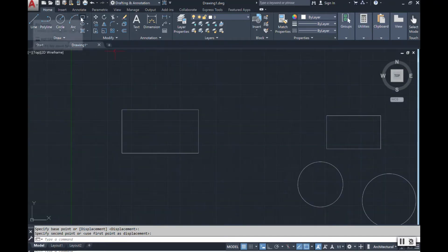Remember, when you pull in a rectangle, you have an object that is 1 unit when you use that rectangle command. When you click on this rectangle, it selects everything. But if you want to break up this, you will use something, remember, that is called that explode command. What I'm going to do here is go ahead and make one of those 3D or 3-dimensional rectangles or boxes.